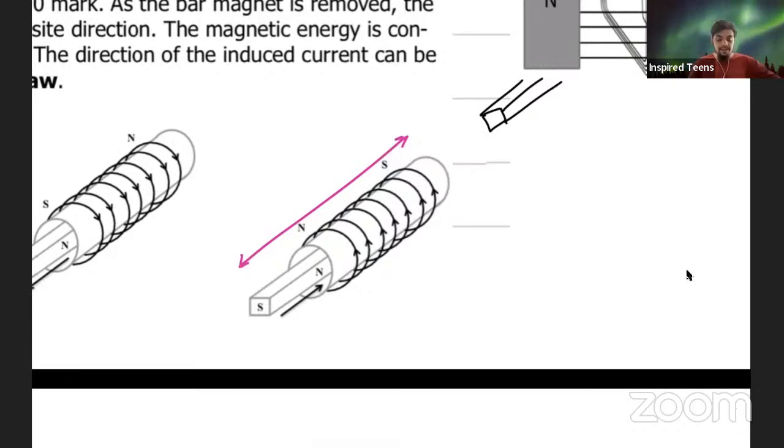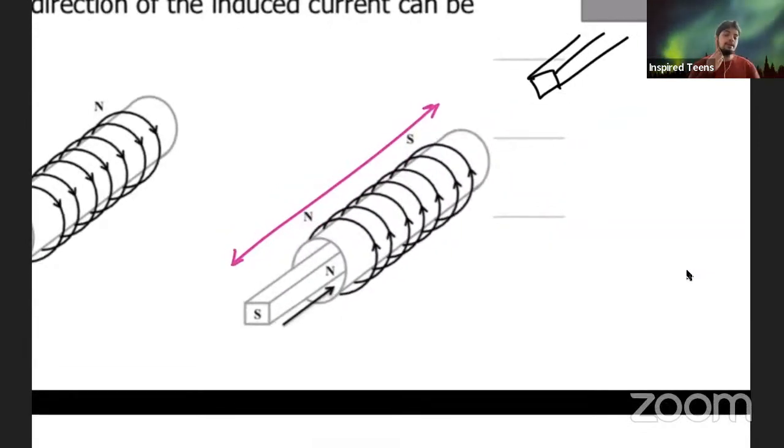Okay, so I hope that makes sense. What actually induces that EMF is the change in magnetic flux. Again, magnetic flux is the amount of magnetic field lines that touch the area of the conductor. In this case, it's like a solenoid. And that's what magnetic flux is. And how do we induce an EMF, or how do we induce a current, on this conductor? By changing that magnetic flux, constantly just changing it.